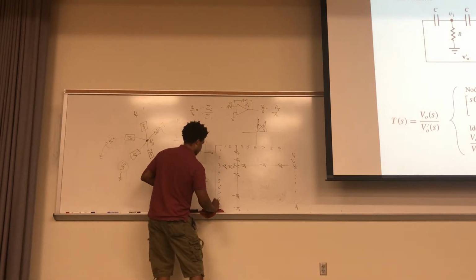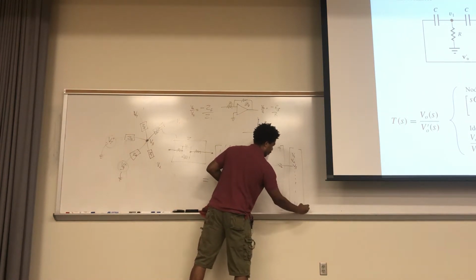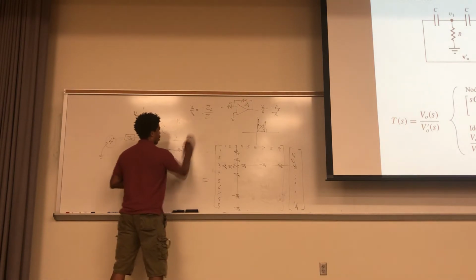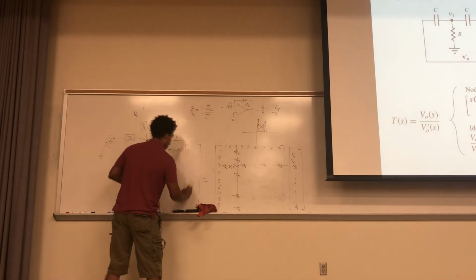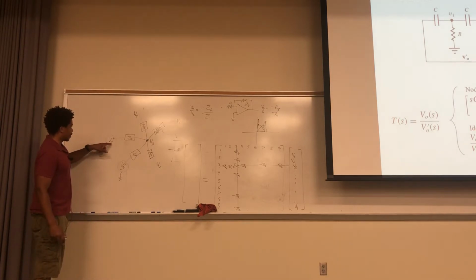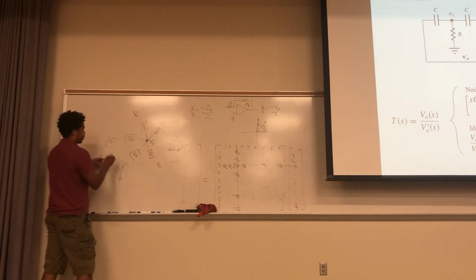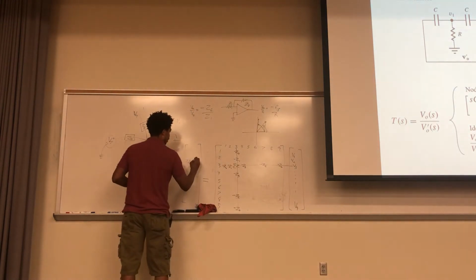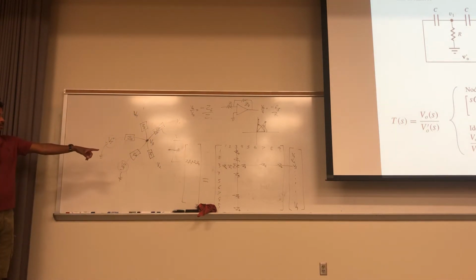So remember, here's the matrix, and here's your unknowns you're looking for. But over here are going to be all of your sources, and they're all current sources. Everything's 0 except for where you have this. So for this row right here, I have this piece and that piece. So right here, I'm going to have a Z2 V7 plus a Z0 V9. Yeah, I'm done with that crazy element right there.